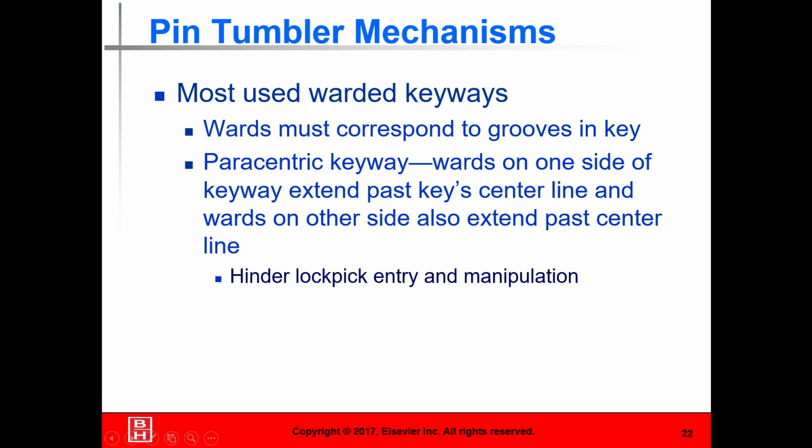The warded key corresponds to the grooves in the key and the paracentric keyway. Wards on one side, key extends. So it's not only up and down, but you have the grooves on the side of the key. So they have to match also. You have the tumblers that are matching, and you also have the side mechanism that's matching. So it makes it harder to pick locks if you have to look at it from the side and the top view. And these are some of the different things that we want to look at.